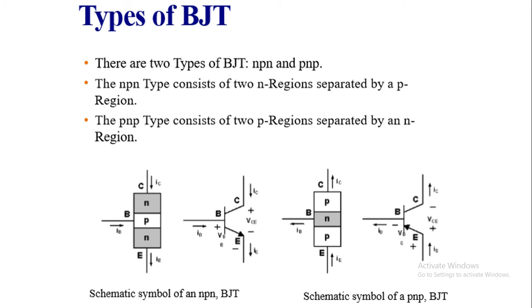And in this NPN, the currents appear here. In the NPN we have the outgoing current from E, so the arrow is pointing outward. And here are the voltages across the NPN. We have VBE, which is the voltage between the base and the emitter, and VCE, which is the voltage between the collector and the emitter. Okay, and there is also another voltage, which is the BC voltage, or the base to collector voltage. Okay, we reverse things with PNP, and the diagram shows that.